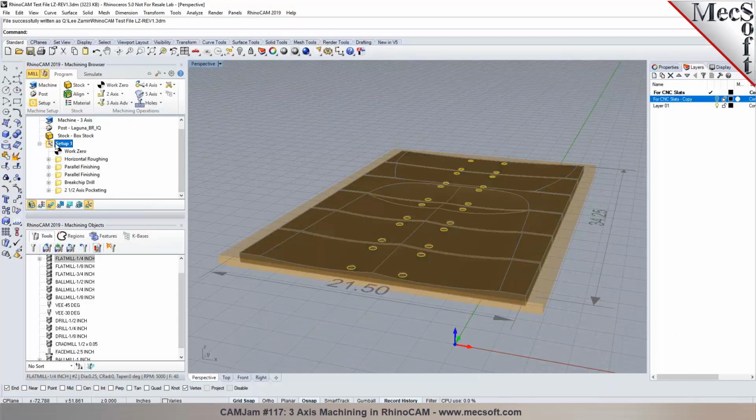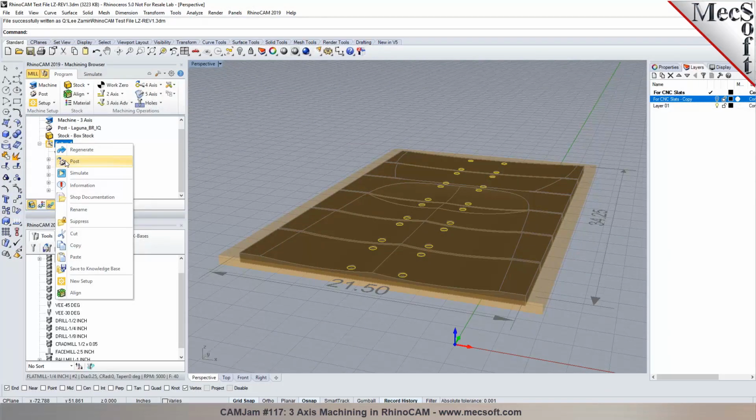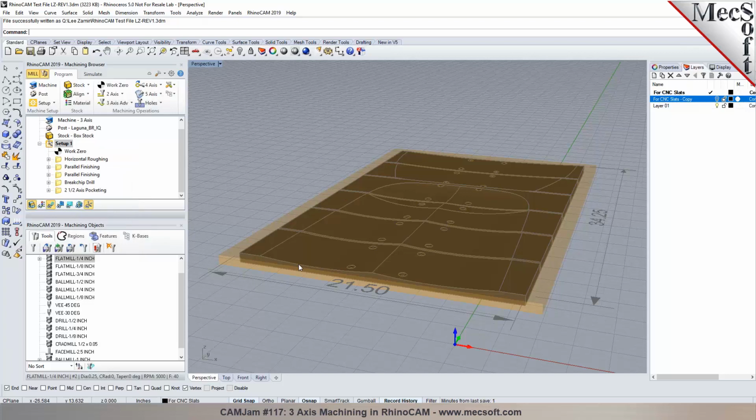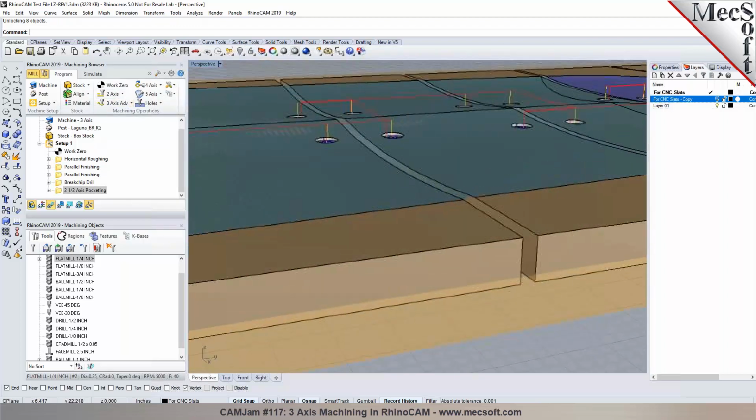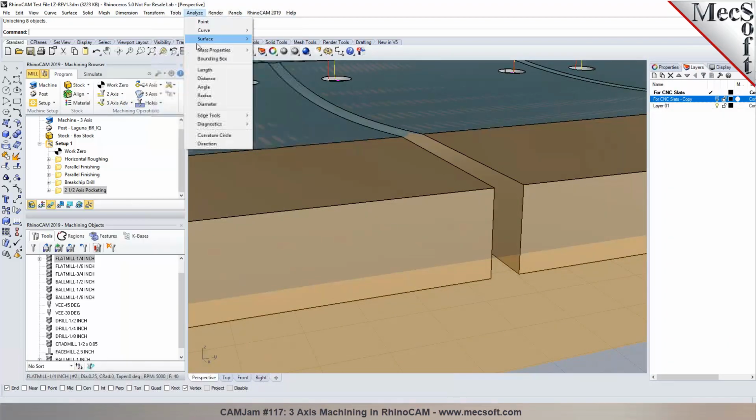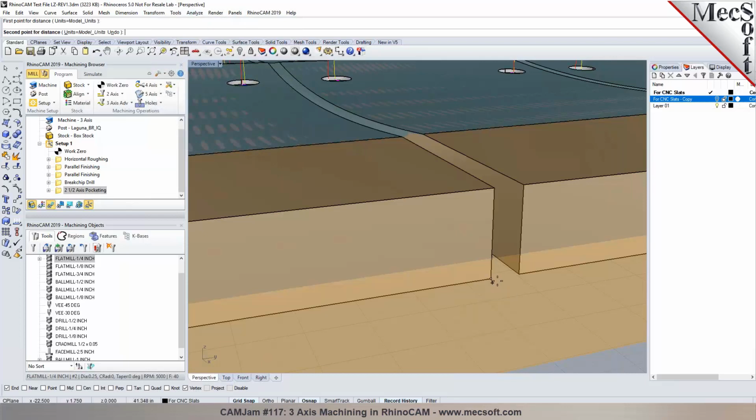Can you try, with tabs, cutting out those 6 slats? Absolutely. So let me go back in here. I'm going to unlock those objects. I want to do what's called a profile cut. So I'll check the gap between the two, analyze distance, and make sure I can fit a tool in here. It should be exactly 1/4 inch.